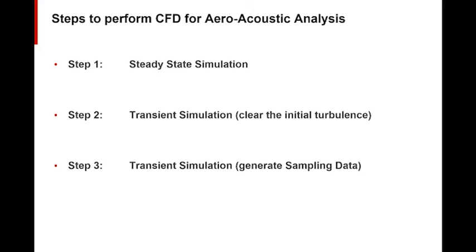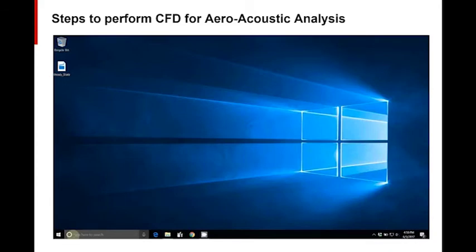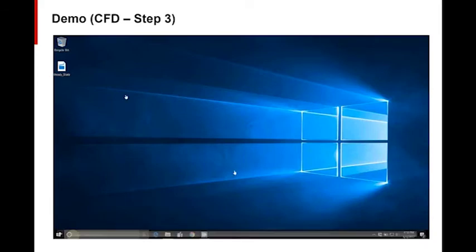And to set the boundary conditions, we go to the analysis condition wizard and select the condition wizard. It's a wizard-driven boundary condition setup, so it will walk you through the steps. The first step we want to do is enable the LES simulation model for the simulation, and we're going to choose options for the LES simulation. And as you can see on the right-hand side, the options will be enabled and disabled based on what we choose, and they will be added to the left-hand side tab.